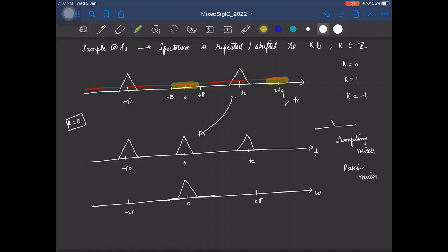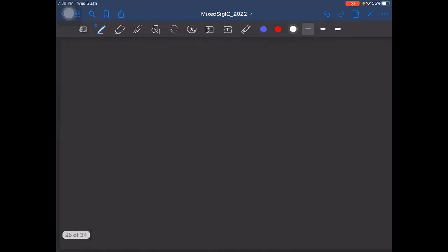So what we have to do, so this will be what? 2Fc minus B, right? So this will be 2Fc plus B. So we need to have a filter. I didn't draw it properly, but it'll look something like this, right? That makes sure that the frequencies from which noise can alias back are attenuated to a reasonable value. Okay. And so essentially we'll have this anti-alias filter, which I call AAF. So this is essentially now a bandpass filter, right? And then you sample it.